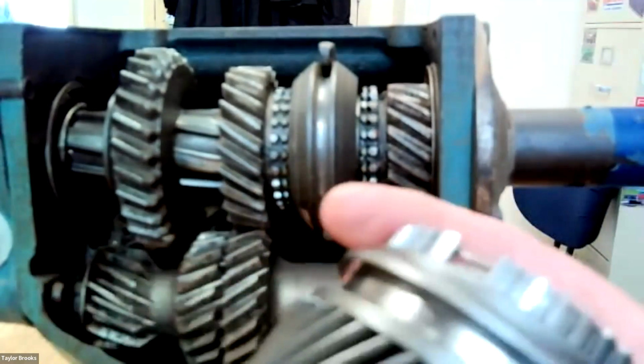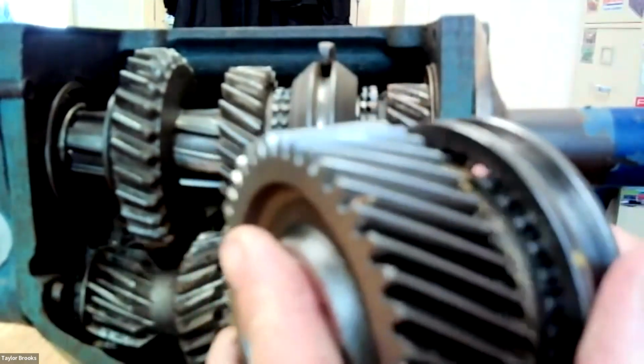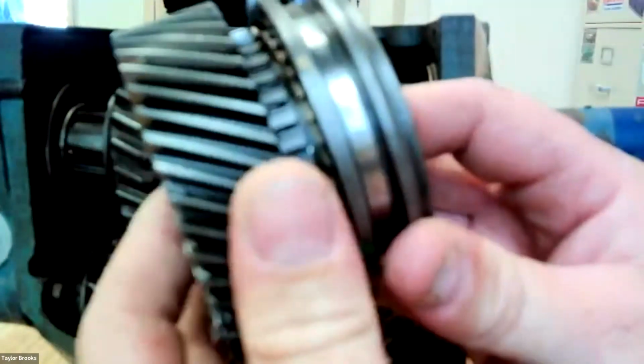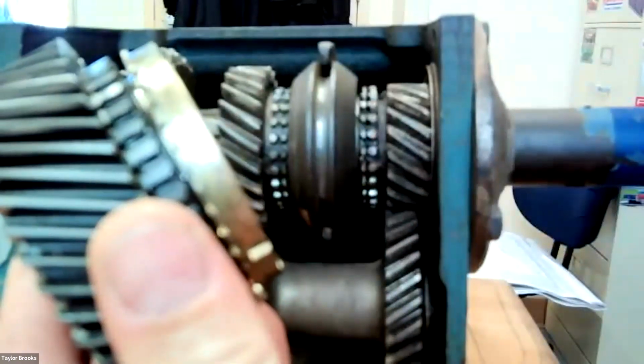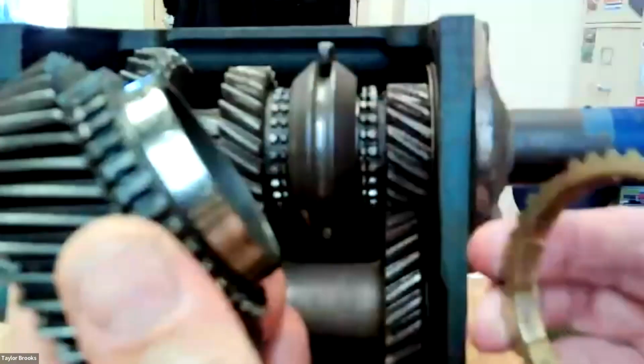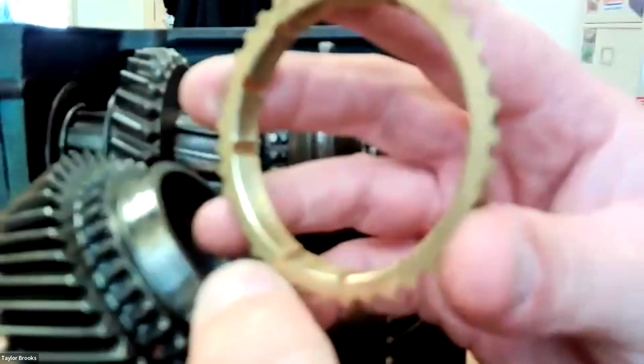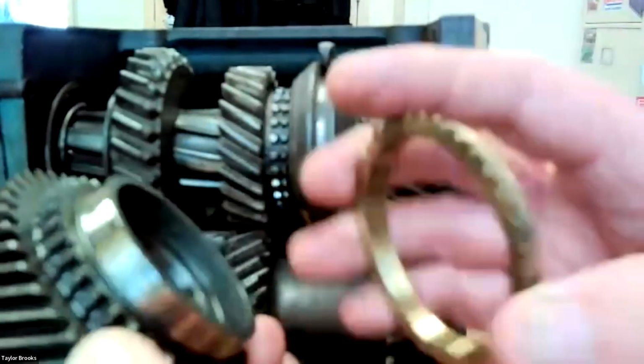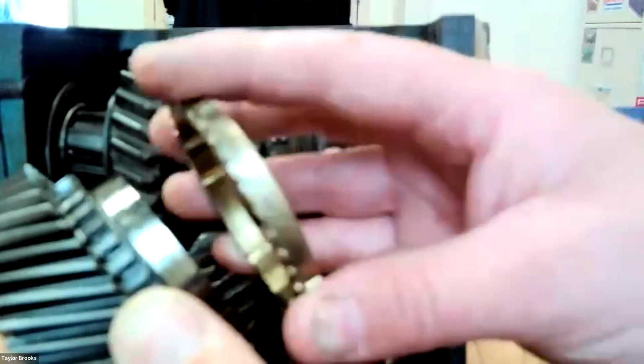To get a sense of that, to see the components individually, I have my Subaru synchronizer right here. I can separate the hub and the slider. I can separate the blocker ring. Now, inside of the blocker ring, I have those little fine metal grooves, and this is a full brass synchronizer sleeve, and that is going to act against this cone.